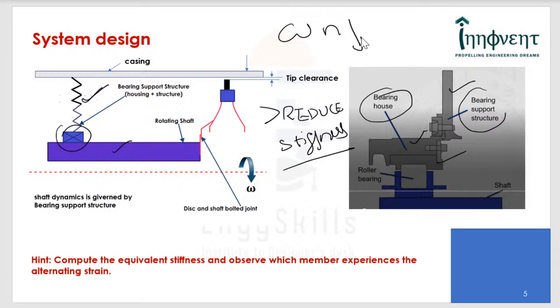Secondly, this is the only structure we would explain in detail. This is the only structure that would provide the damping, especially in a gas turbine situation, because the whirling shaft may not undergo strain alternation, because for any hysteretic damping to be produced, there must be a strain alternation which cannot happen in the shaft, and that comes from the static support structure.